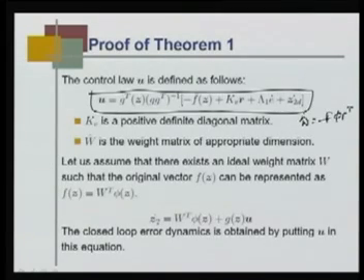If I have this weight update law for estimating f hat z, then this controller will give me the result that the actual output will follow the desired output. Okay. So, in this control law, Kv is a positive definite diagonal matrix,